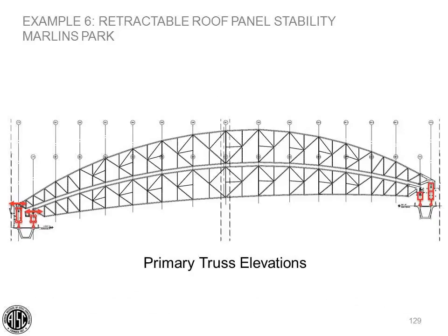Here the upper panel is parked over the lower panels. In order to avoid large thrust to the wheels and rails, we provided a release mechanism on the low track side on the left to allow the trusses to move left and right at the left end without building up large struts. This means that all the lateral loads in the left-right direction are resisted at the high track end on the right side.